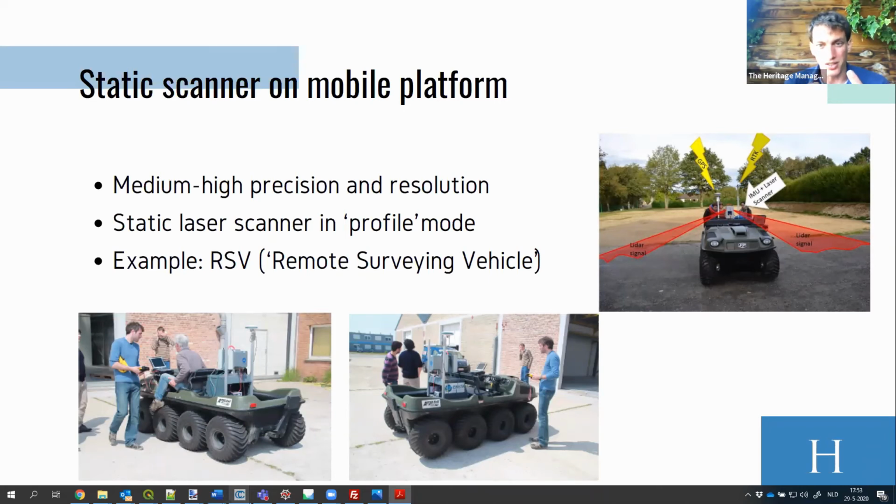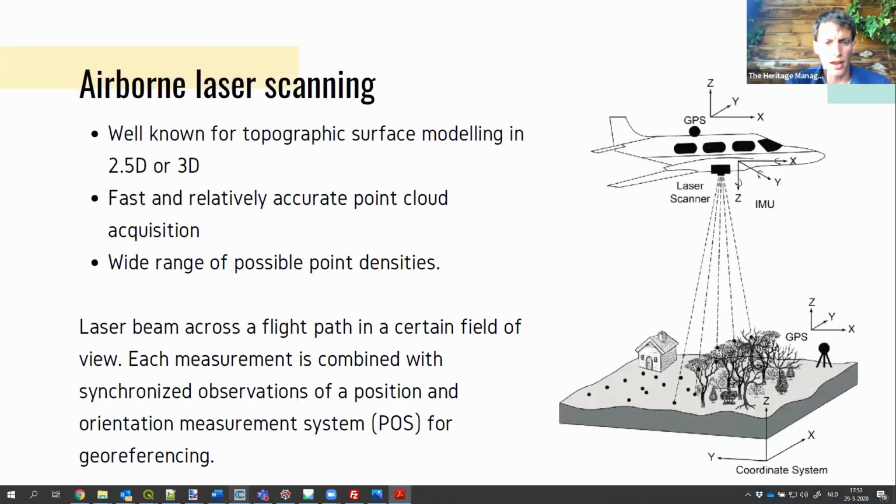If you do a measurement with a speed of 500,000 points per second using your laser scanner, then you need to know while moving which point has been taken when and where. And in order to do that, you need, of course, a time stamping of your GPS and the time stamping of your motion sensor, which are obviously not measuring data with the same speed as a laser scanner.